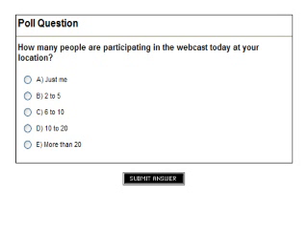Mark, I have a question regarding that disinfection. If you're putting in too much chlorine, isn't that the issue of the dechlorination then? That's correct. As we'll talk about later, you put in enough chlorine to take care of what could occur. You usually look at the outer envelope of the concentration of pollutants that can come in. So you're going to be over-chlorinating at that time, so then you tend to over-dechlorinate in order to get the residual down to acceptable levels. The residual is the problem. It's going to be toxic at very low concentration.